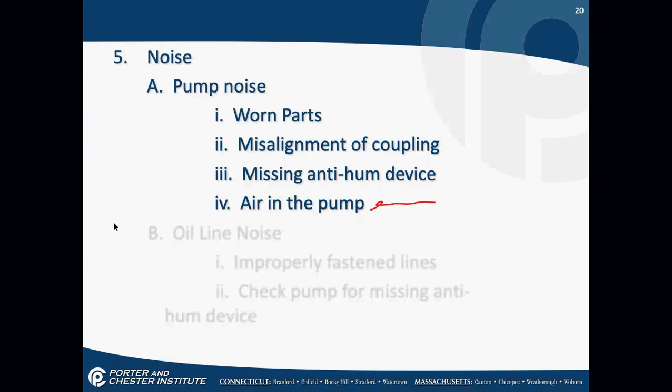Because air. If you have air in the pump and there recently hasn't been service, what do you need to do? Anybody? If there's air in the pump and there hasn't been a recent service call, they haven't run out of oil, no one's been there recently, and you find air in a pump, what do you need to do?